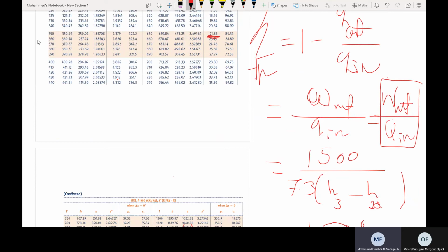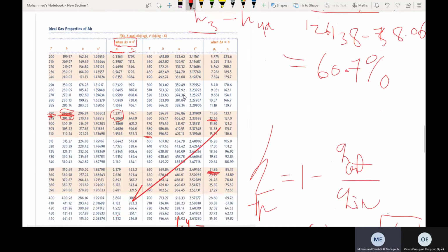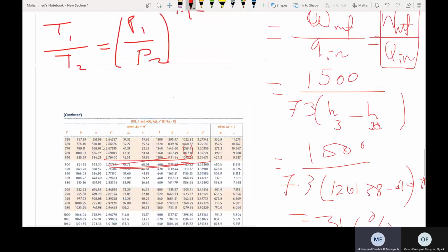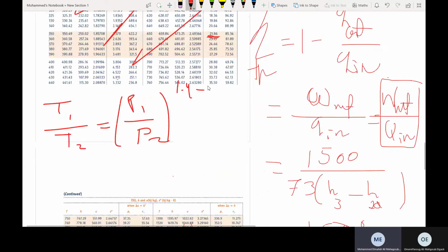So yeah, T1 over T2 is going to be equal to P1 over P2, to the power (k minus 1) over k. No ratio relationships, remember. k is 1.4, you are not even going to use the tables, okay? So just delete the tables, because this is called the cold air assumption again. And keep repeating that so that you don't forget it.